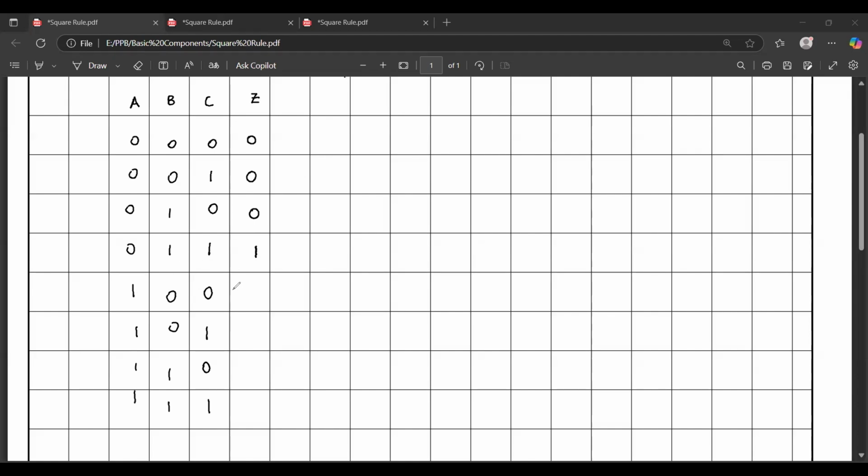And what about here? Well, we don't have to mention that. Why? Only one sensor is detecting. For the other three instances, the output will be 1. Here two sensors are reading, here two sensors are reading, here all three sensors are reading. In the question, they have clearly said at least two sensors. If at least two sensors read on, the motion is recorded, then the output will be 1. That's the idea behind this.